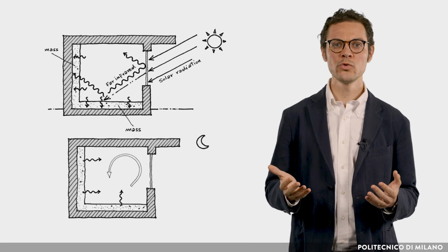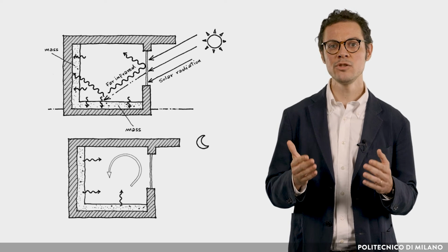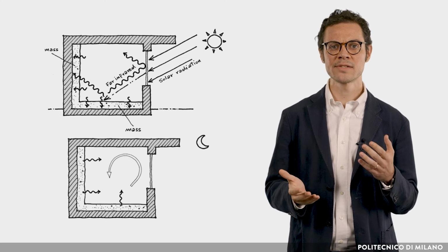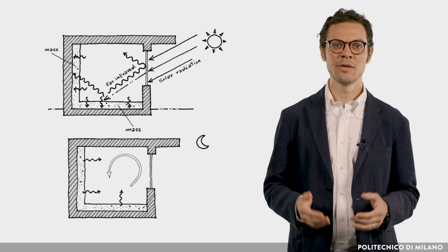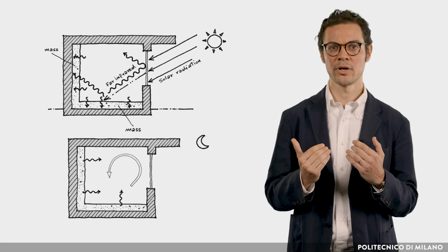The construction of roof should be characterized by medium heat storage capacity to balance temperature swings between the daytime and the evening hours. The mass should be placed in the inner part of the construction. The average area of the openings should be about 30% of the area of north and south facing walls to ensure sufficient ventilation for comfort and for cooling the structure at night. Preferably, openings can be placed mainly above the staircase or overhangs.